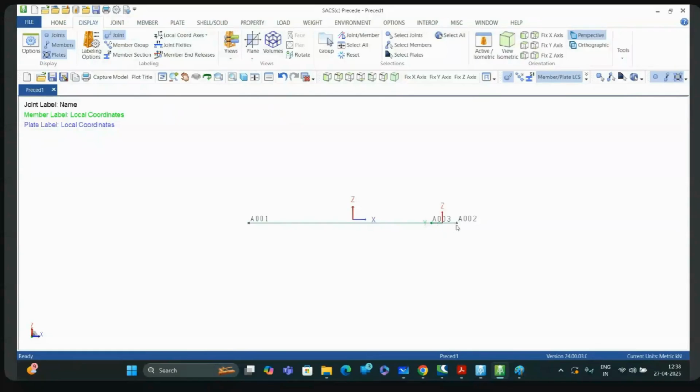The perspective will show a view like inward, what we see with our normal eyes. If we look at a veranda, how will it show? It will show inward, right? So that is perspective. If you want to see everything just behind, you click on orthographic. Orthographic will adjust as if we look from each point. Is this view clear? Yes, sir.